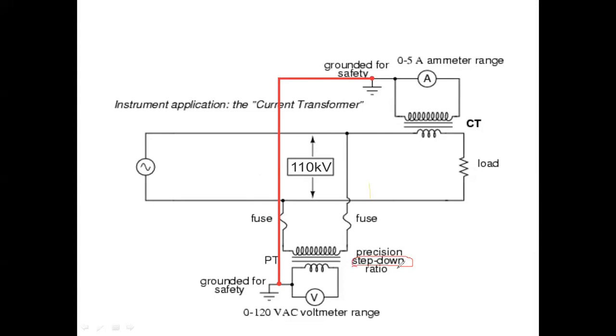So many questions are coming. I am talking about the tricky question. You already know that the potential transformer is a step down transformer. But if someone asks whether the number of turns in the primary side of a PT is less, is that correct or not? Just remember this diagram, because this is the step down transformer. The primary side is always connected to the feeder line. This is the feeder line, and this is line and this is neutral, or maybe vice versa.